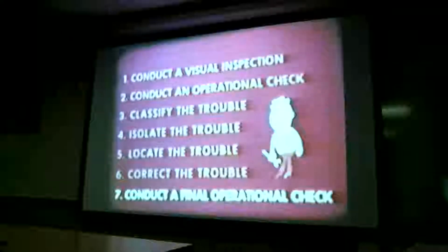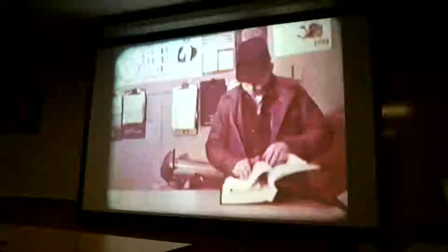Before we take a closer look at all 7 steps, let's consider 2 important things that you must first do before you begin to troubleshoot. Familiarize yourself with the aircraft's characteristics. Do this by consulting the handbook of maintenance instructions, or in the case of newer model aircraft, the maintenance instruction manuals. You're not required to memorize complete aircraft systems, but you must know where to go for the answers.